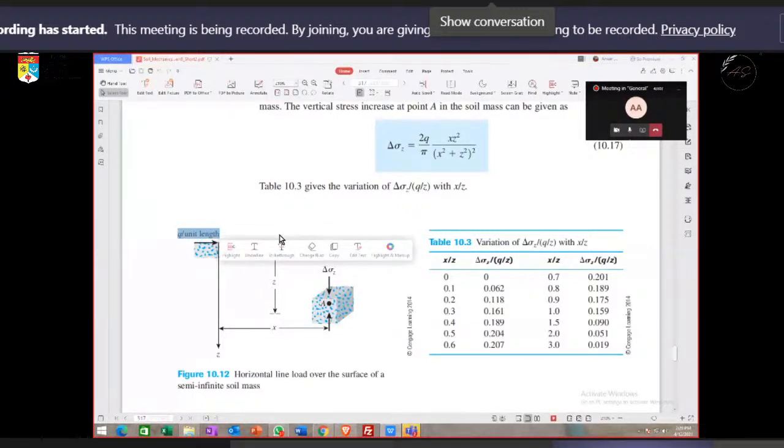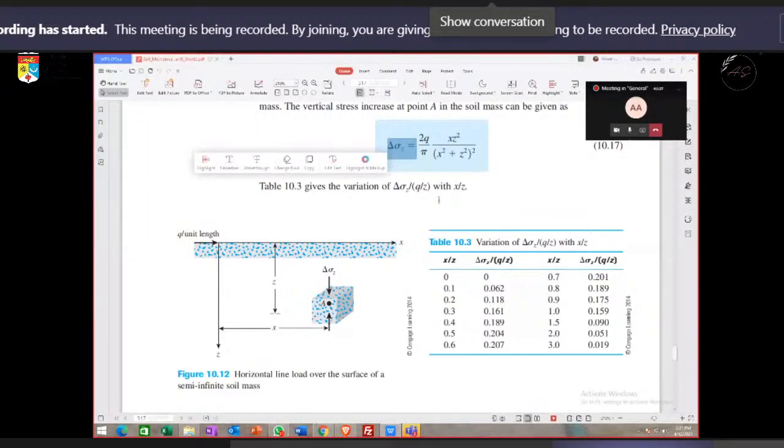Maybe you put some support to the wall at the bottom, and then it could be the lateral or horizontal line load. So the same thing, we are given the equation. We can just use this equation, or to make it simple, using a table, so we can calculate the stress increase due to horizontal line load.